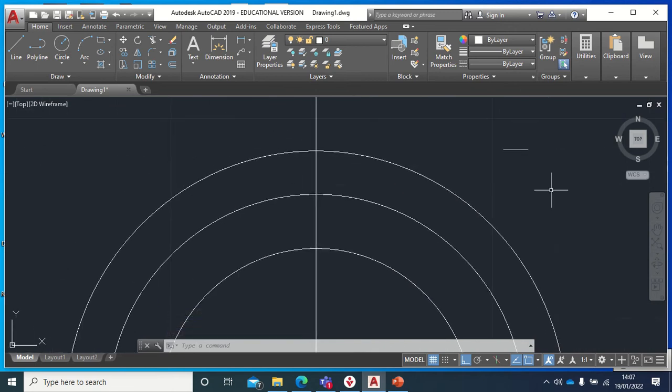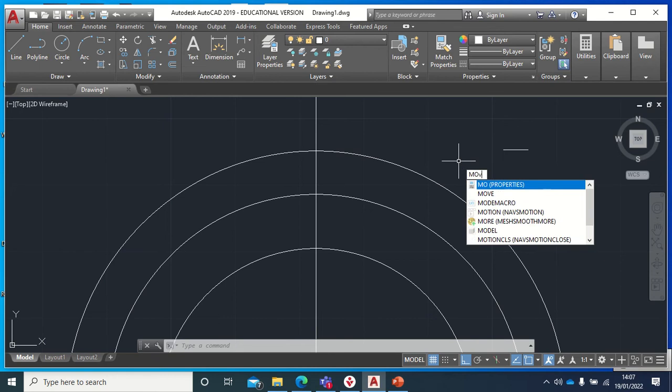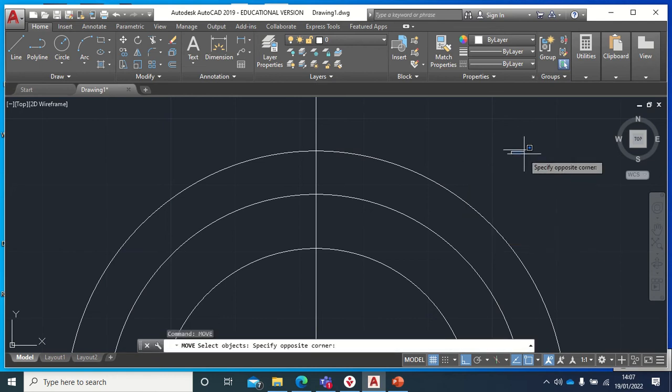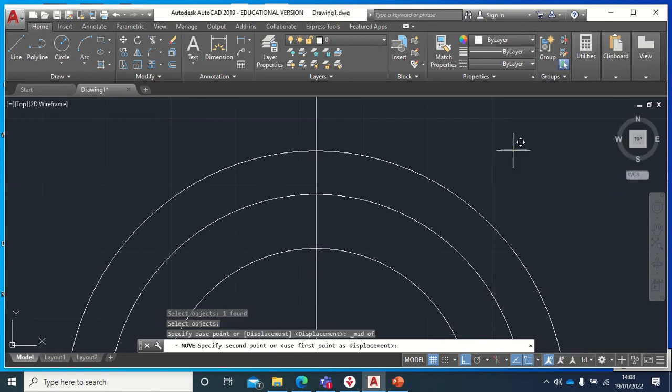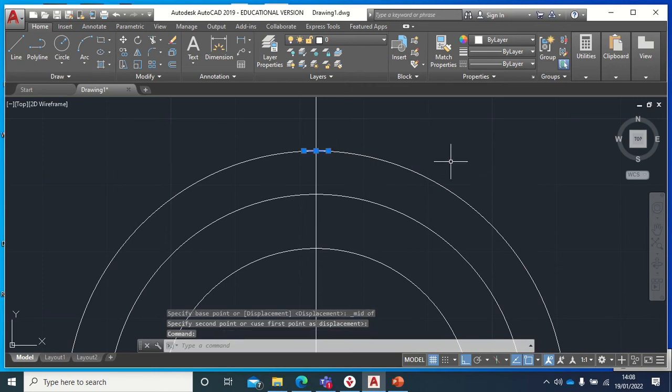And then let's move it. Do you know how to move? I'm going to move it and put it here. So I'm going to just move this. And then I will use shift and midpoint, so that I can pick the midpoint and take it to this one here. Take it here. So, you know, I've got that line there. Did you see what I... Yeah. So just draw the 3.822 line and move it to that point there.